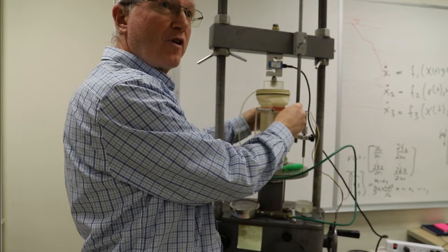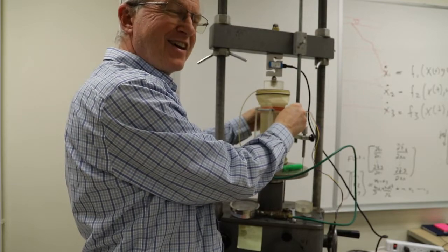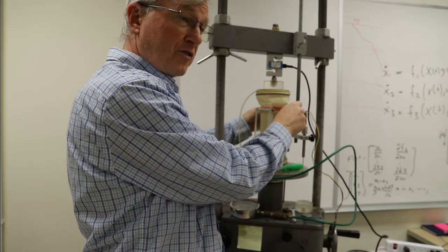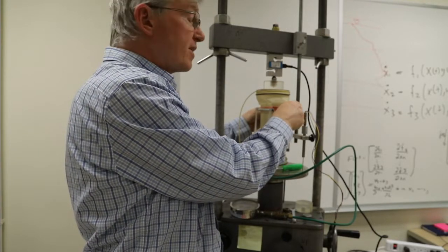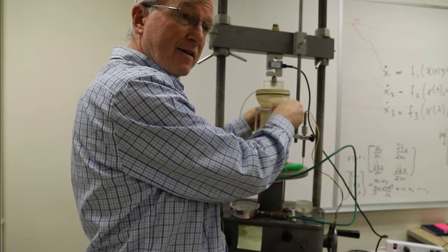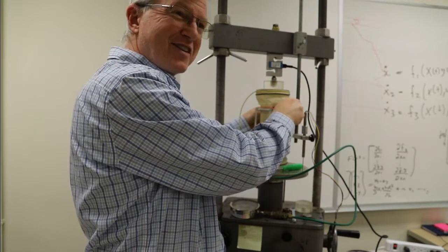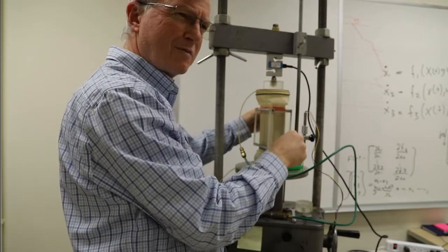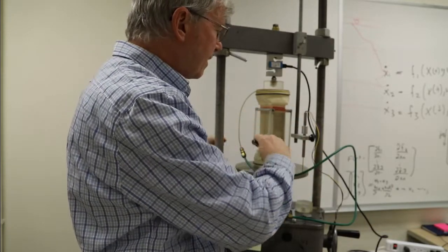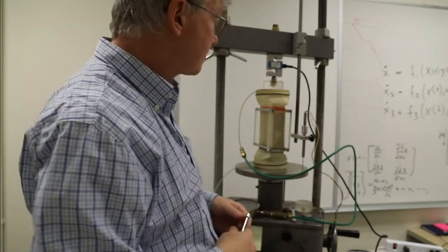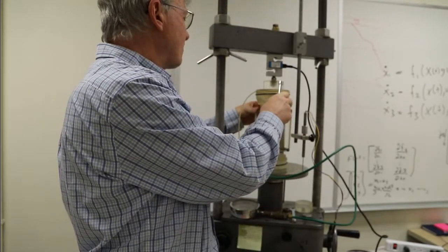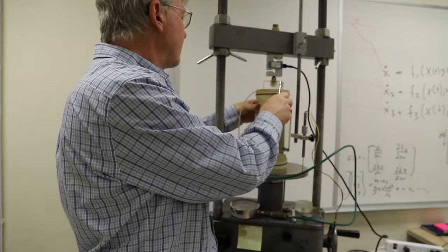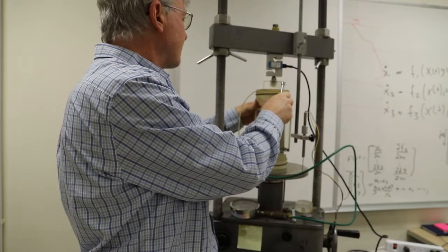And so if you have strain gauges on all of those, you can measure the force with which the sample's trying to do that, and you can calculate a horizontal deviator stress, sigma 2 minus sigma 3, and you can use that to calculate sigma 2. This system isn't set up to do that, so we won't have that data, but you certainly can.